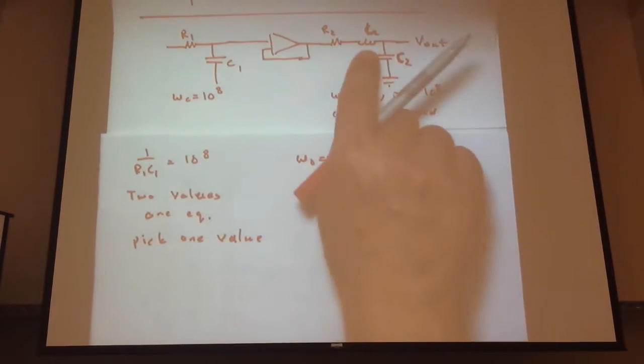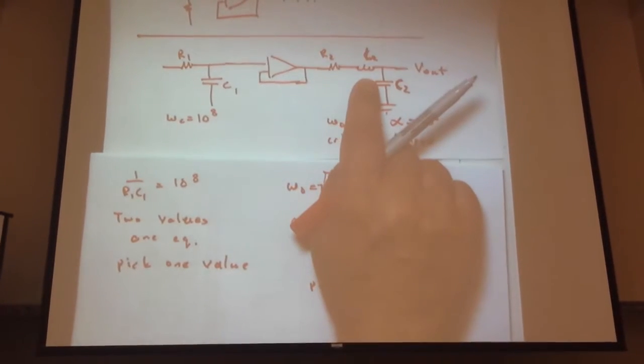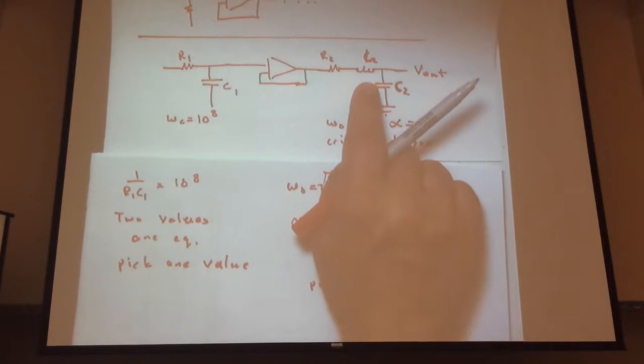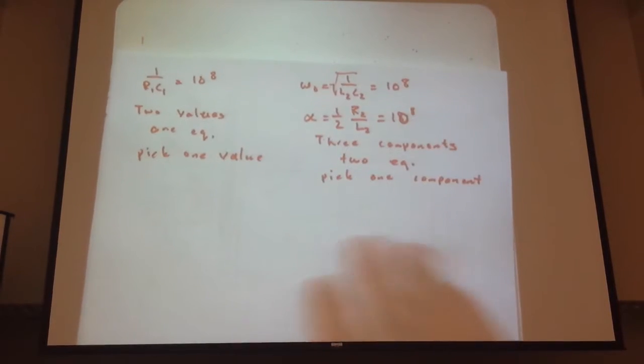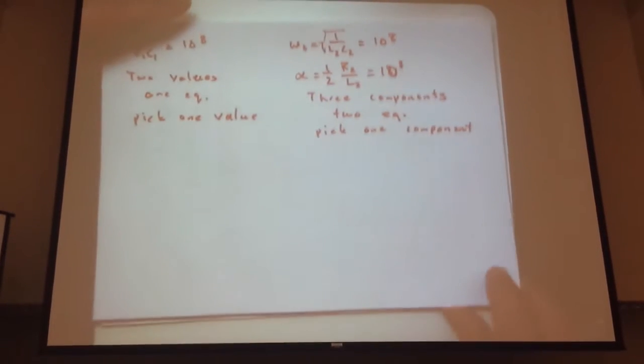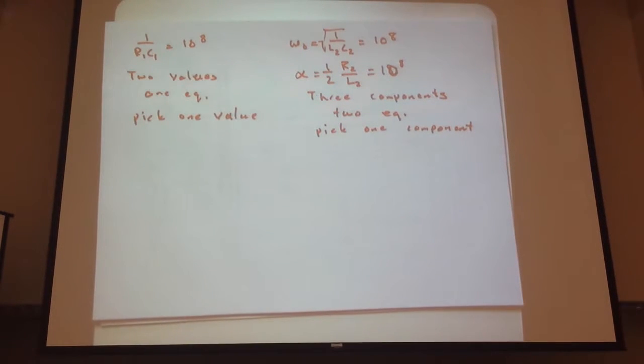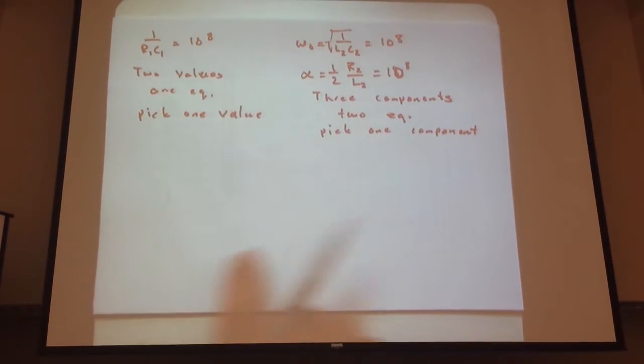So typically, you don't actually want to build inductors. Most of the time, most circuits avoid inductors outside of big power engineering systems. On the small scale, inductors are problematic. Some of the more recent, by recent I mean last 10 or 20 years, substrate inductors are interesting and they're becoming more useful. They also have a lot of parasitic capacitance associated with them.